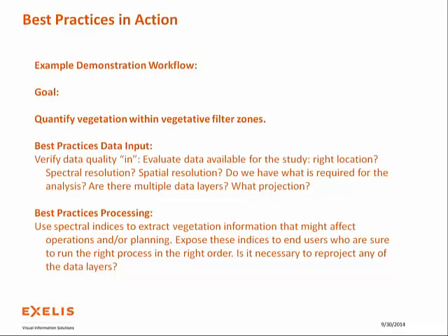Depending on the slope between a road and a waterway, there needs to be a filter buffer zone of vegetation to filter sediment. So if there's any accident or something spills, any of the sediment will be filtered out before it reaches the waterway. The width of those buffers differs depending on the slope from the road to the water channel. So that brings us to what data we need.